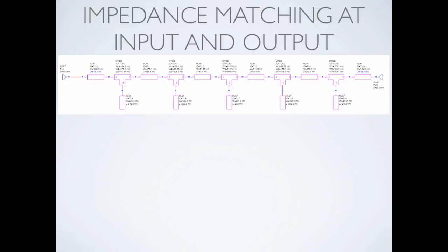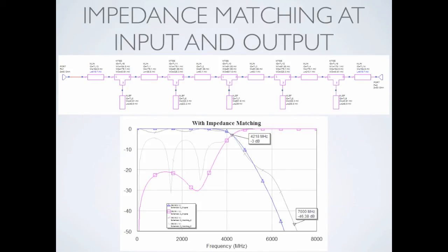The weirder part came in when we used a quarter wave impedance matching at our input and output of our LPF in order to normalize it to 50 ohms. We suddenly introduced an equal ripple of about 2.5 dB at our passband, but we actually wanted a maximally flat band. After hours of tuning again and again to try to reduce this ripple, we found that the flatter we try to make it, the smaller our cutoff and bandstop frequencies became. It started to deviate away from being an LPF into something really odd.